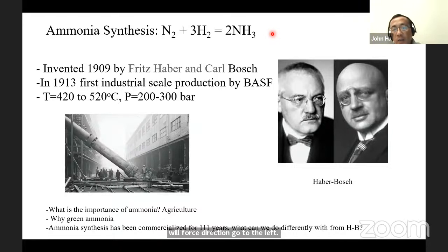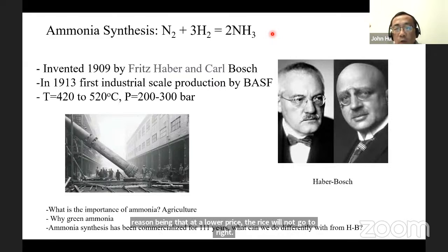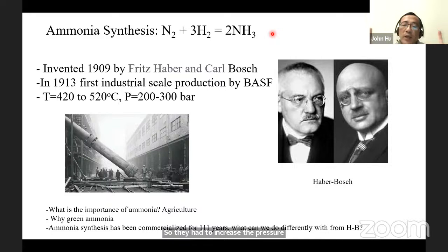So the student just mentioned that you need high temperature to activate nitrogen. He's correct. That's why these 2 gentlemen 100 years ago tried high temperature, but they got a very low yield. The reason being that at a lower pressure, the reaction will not go to the right. So they had to increase the pressure to force the reaction to go to the right. So they counter each other.